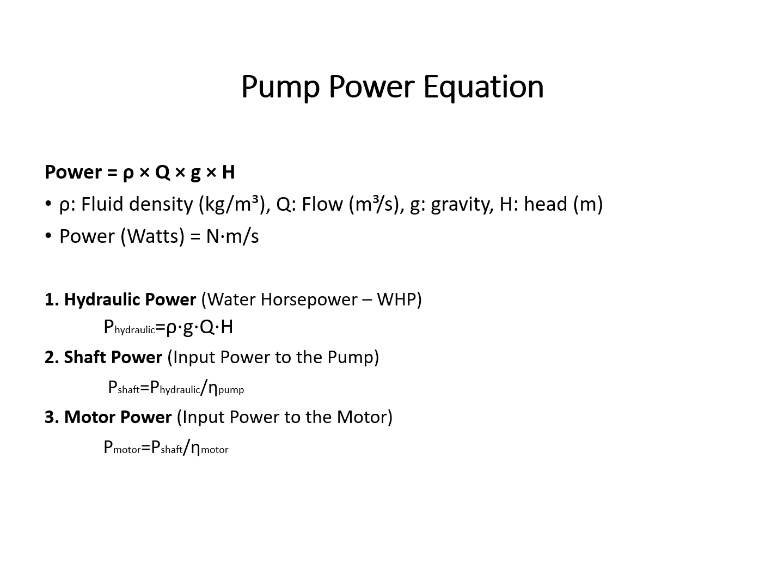If your pump is 100% efficient, meaning that all the power in will be converted to the shaft, then this will be 1. But actually, it is less, like 80%, 75%, 60%. So you will add this percentage here. Okay.